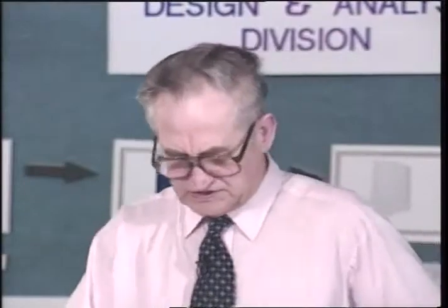I thought it would have more effect than that, because by varying the pitch diameter, of course, you are loading your threads unevenly. But evidently what happens is that though you are loading them unevenly, you're spreading the load around to where you get more yielding, and it'll still carry the load. So some of the people who did the testing were surprised that it was that good.